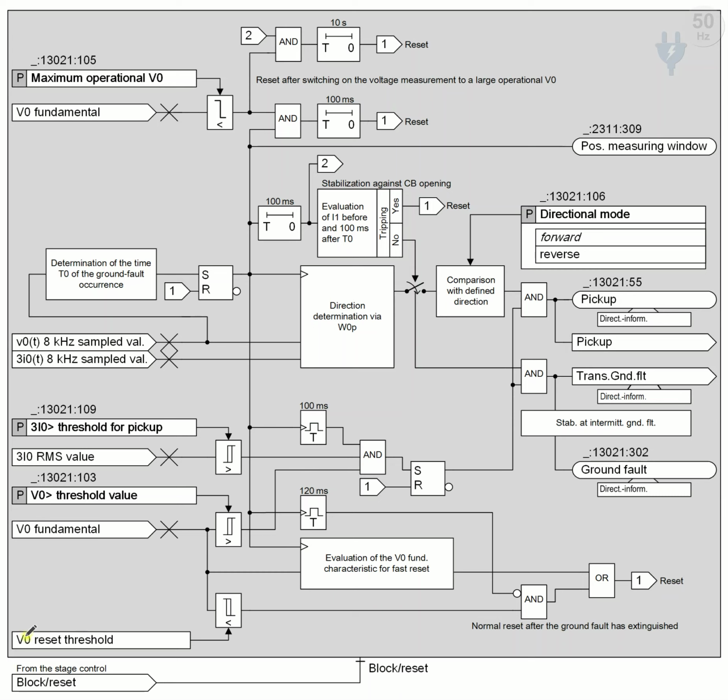First, the zero sequence voltage reset threshold is 2 volt. Mostly it depends on the value of the maximum operational threshold, but right now we consider it as 2 volt. Normally it is internally set as 2 volt.